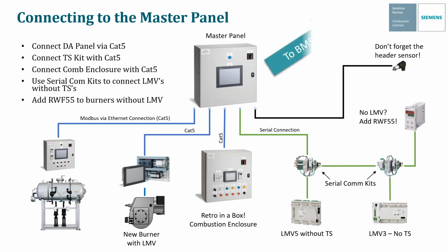Once you have all of these things connected, you can also connect the master panel to the BMS via whatever protocol they require. So that's a quick summary there, how we connect everything up to the master panel. And we're going to reference this page a couple of times throughout the presentation to discuss how we set up the master panel.